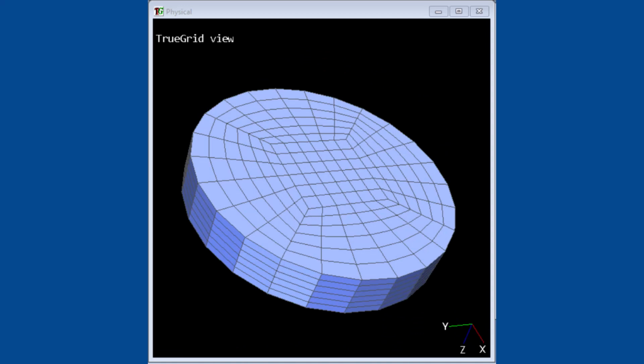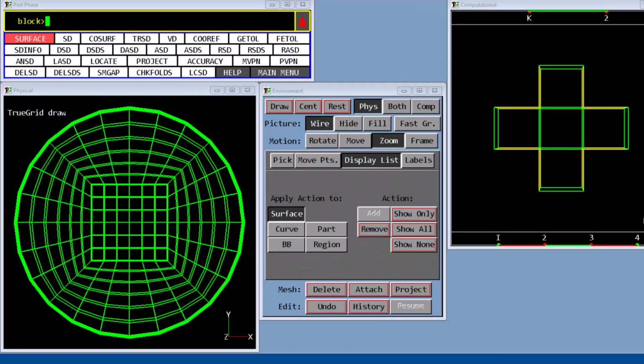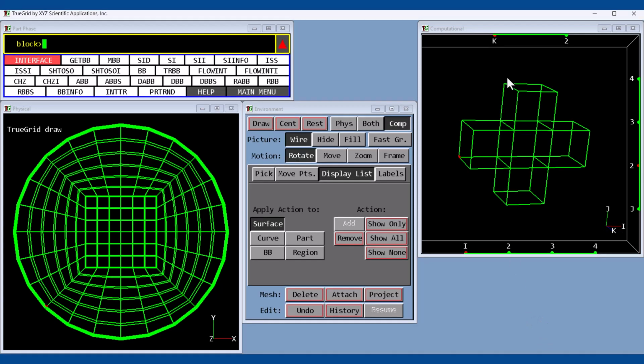To do this, we first glue the adjacent wing block side faces to one another so that they share the same nodes before smoothing. If we don't glue these block boundaries, the smoothing algorithm will consider all of the wing block side nodes as fixed, but we want them to participate in the smoothing. By gluing the side faces, we remove all of the collateral nodes and incorporate all of the disk nodes into the smoothing process. I have selected one of the 2 faces I want to glue together.